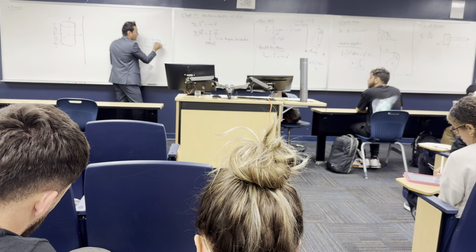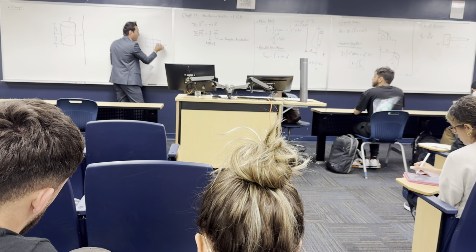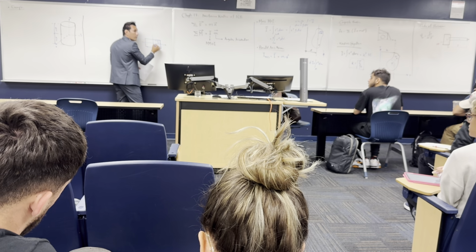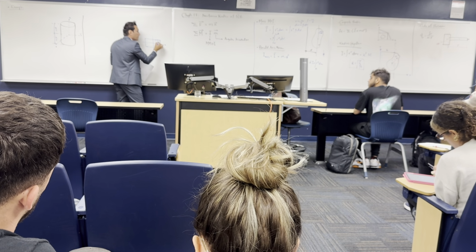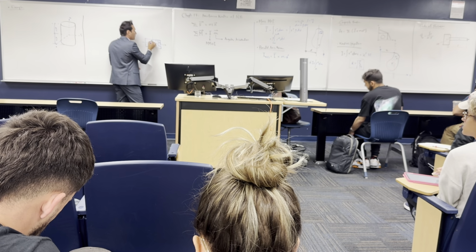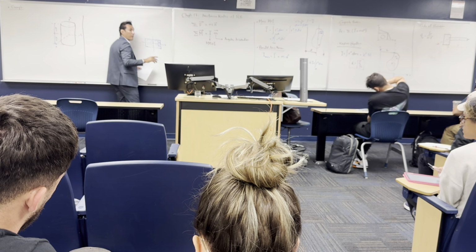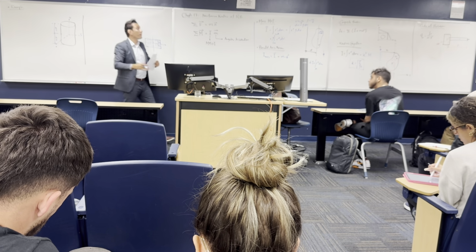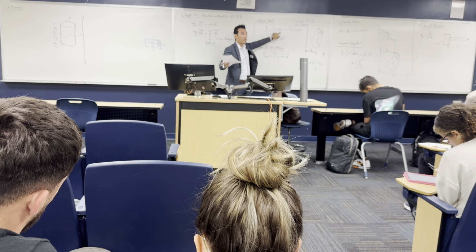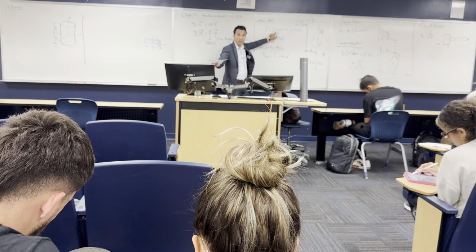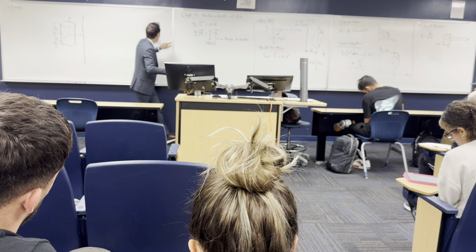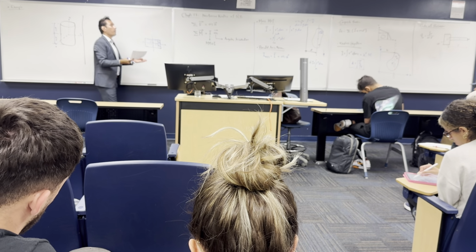This distance is positive, right? If we are getting all the masses in this block, it's going to be positive, right? But all the masses here are negative. So this r is positive, this r is negative. Same thing here. This is positive, but this is negative. If we are getting the second moment of mass, which is the mass moment of inertia, r squared multiplied, it doesn't matter if it's positive or negative because r is going to be squared. So if it's negative, it's going to be squared and it's going to be positive. So you are going to have all these four blocks as a positive thing.